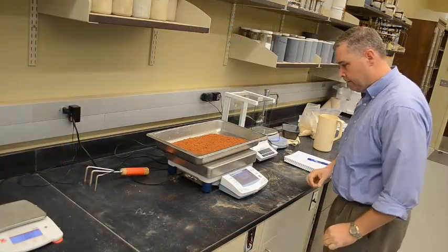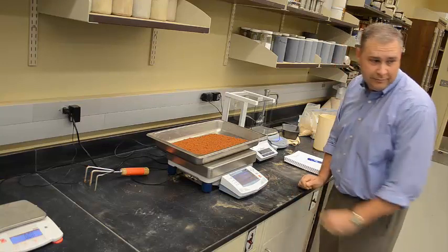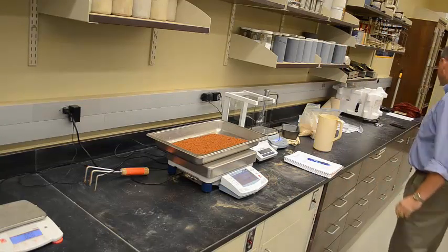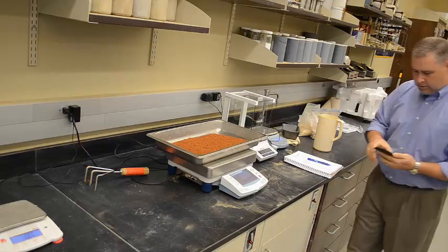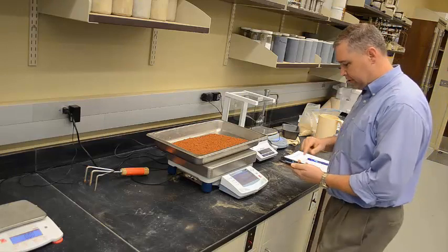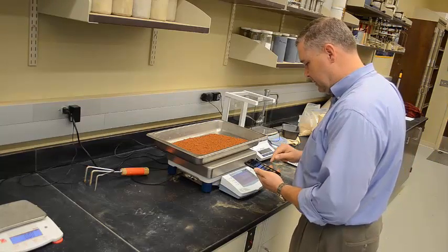Once you have that, you need to get a new weight of the material that's left over so you can estimate appropriately the amount of water to add to it. But this time the water is already in, so you want to add 2% more water to that soil sample. So you might need to use your calculator and calculate what 2% is.